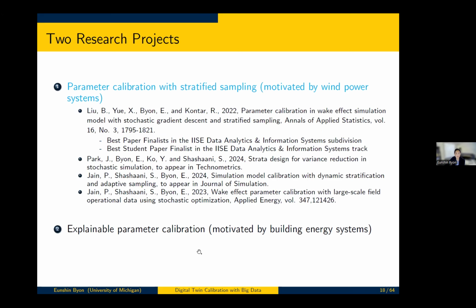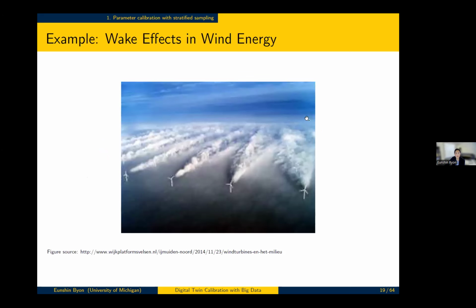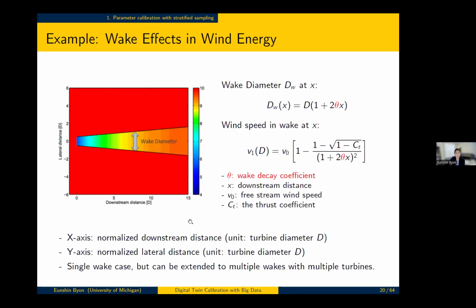And then I will move on to the next topic. So again, we consider this wake effects in wind energy, and we use this Jensen's wake model. And our goal is to calibrate the wake decay coefficient. Later, we used more advanced wake models, but in this presentation, I will use Jensen's wake model to discuss the idea.